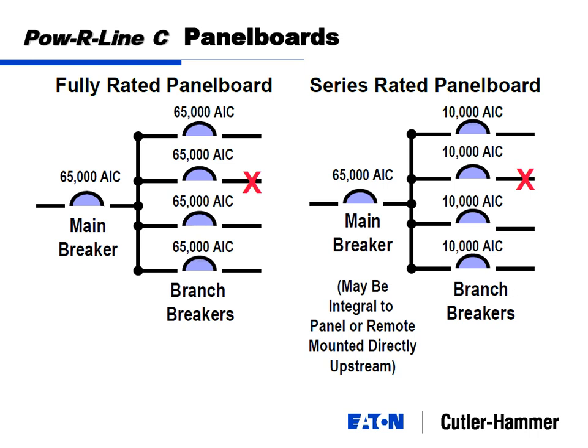Series rated doesn't mean anything in medium voltage. And it really doesn't mean anything in a switchboard construction either, unless you're just using the feeder breaker in the switchboard to feed a main lug only panel. So this is strictly for panel boards. And it's strictly for cost. And cost is pretty important, obviously.